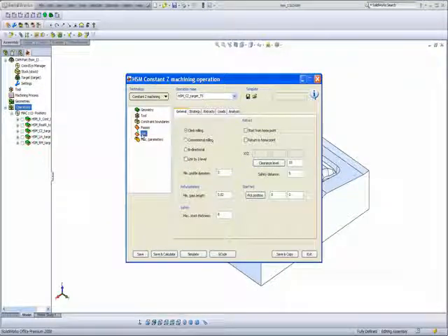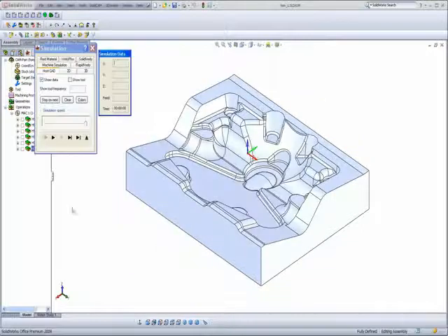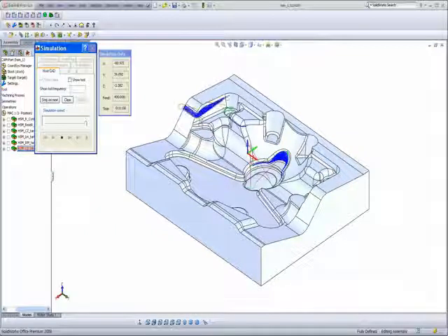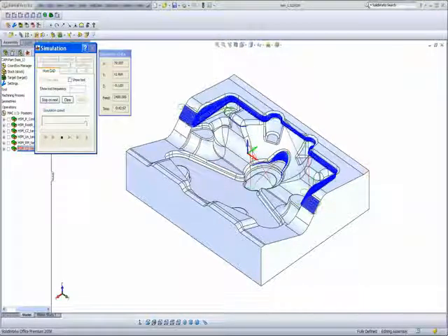In my link area, I'll use bidirectional. And let's do save and calculate and see what the results are. As you can see, similar to before, we're working only on those particular areas, only on the straighter areas right now, because those are between 40 and 90 degrees. Again, it is not working on these areas.